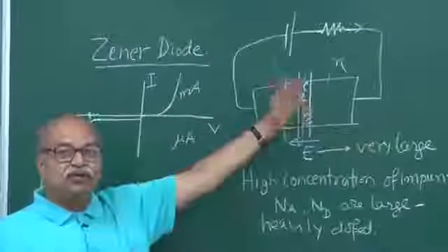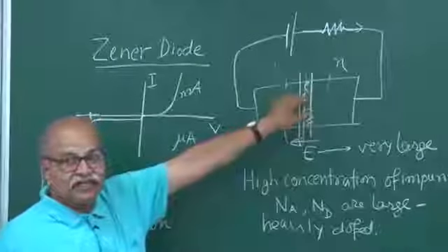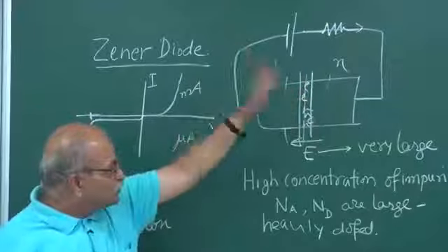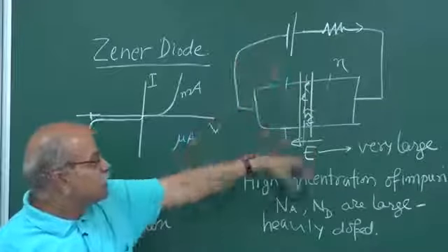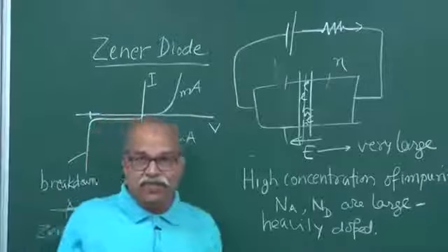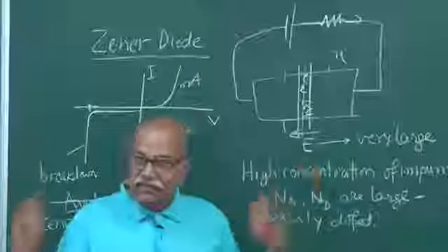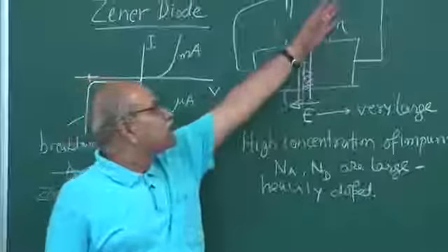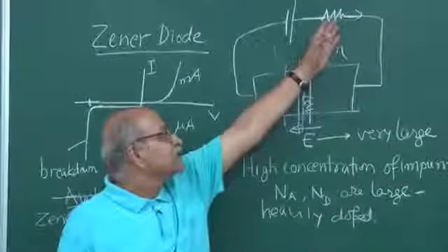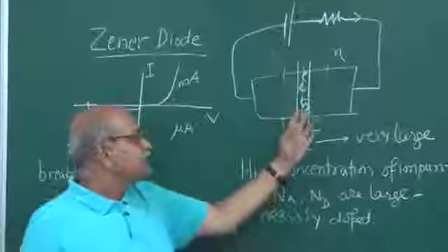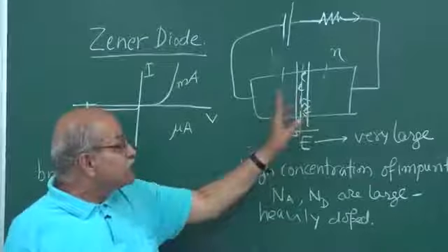The moment it becomes 2 volts, you have all this process starting, and then it cannot increase beyond 2 volts, because at 2 volts itself you try to increase and the current will increase very high, and if you put really more than that 2 volt, then the whole thing can get burnt, right? So you must put a resistor here, so that any extra voltage that drops here and here remains the voltage for which it is created.